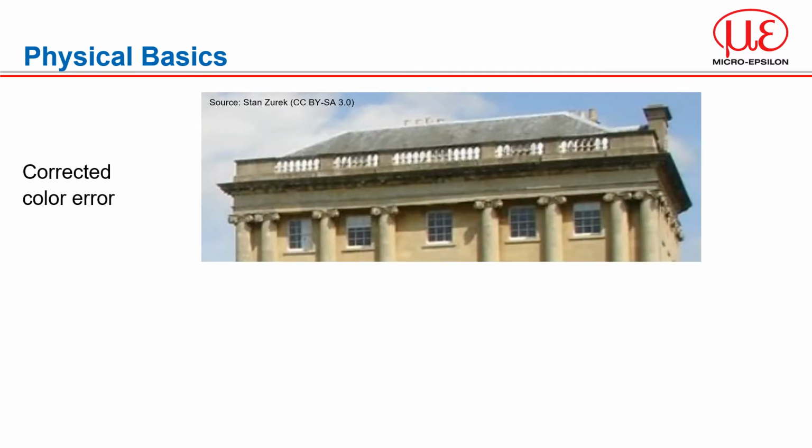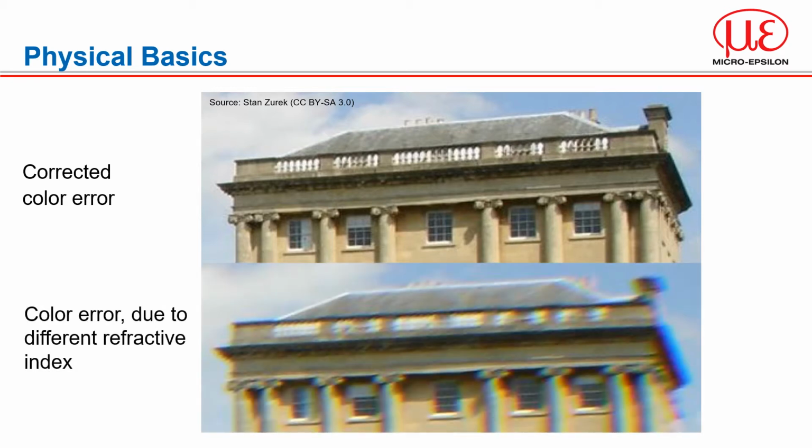Now, in most optical applications, the appearance of different refractions through a lens is best avoided and is corrected to give us the appearance of a sharp image, as without the correction of the optics, we would be faced with an apparently unsharp or blurred image. However, it is precisely this phenomenon, chromatic aberration, that we use to our advantage with the confocal measuring principle.